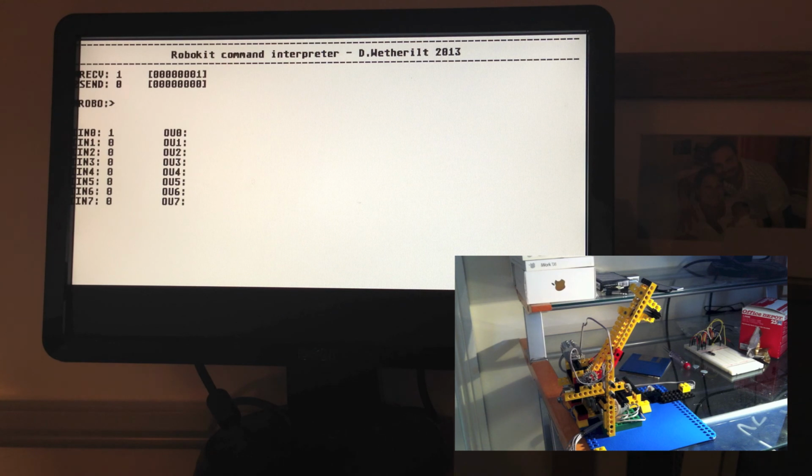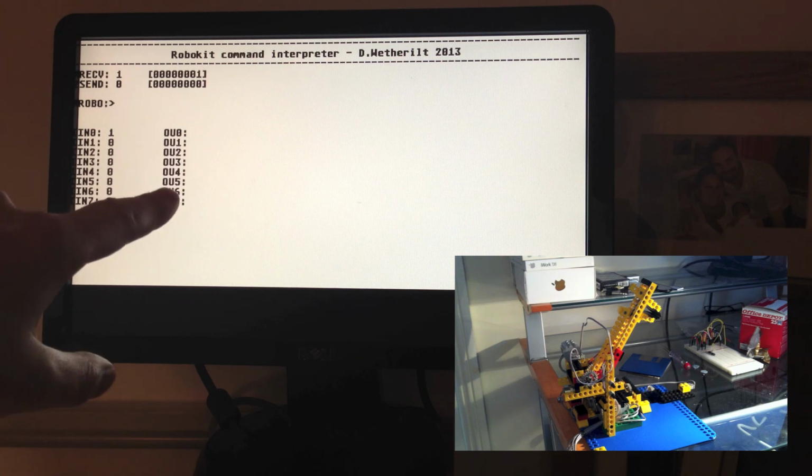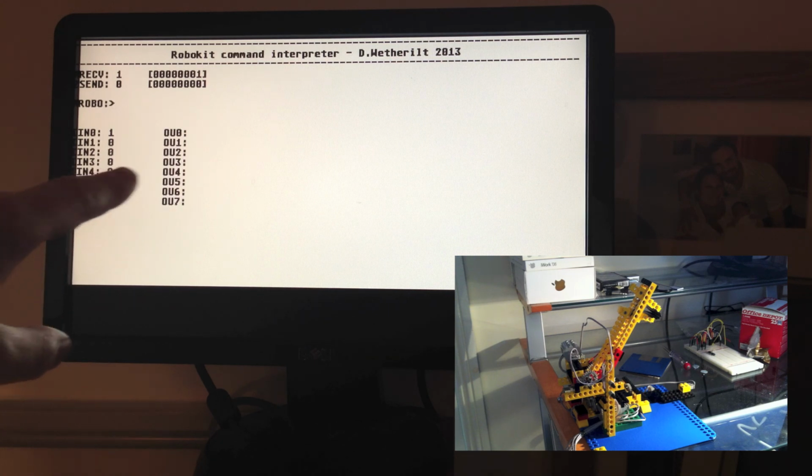So what we have going on is, under the surface we have a state counter which can be enabled or disabled. By default it's switched on, so any time an input or an output state is changed, the state counter pertaining to that channel is incremented by 1. Now this is particularly useful at the moment for the input channels, where I might want to wait for a certain number of pulses on an input channel before I reset an output line.